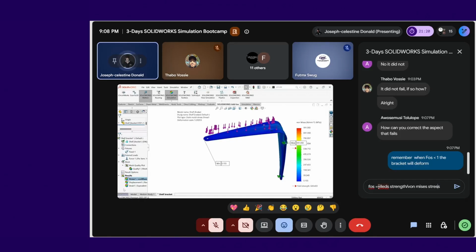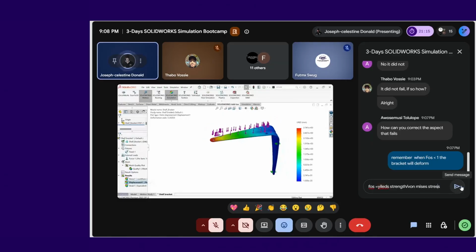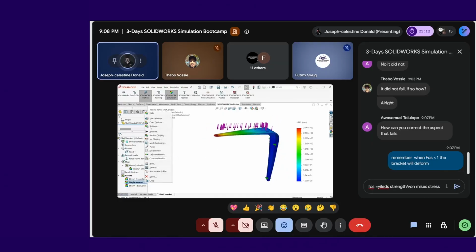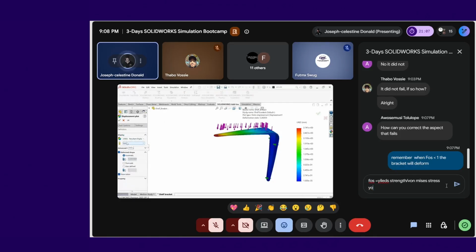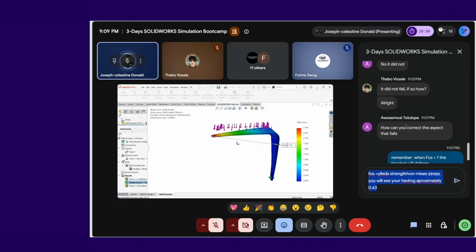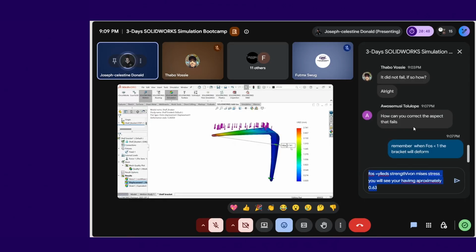Okay, now displacement. Double click and you get displacement. You do the same thing: right click, edit definition, so you get a proper value. It's in millimeters, so you select where your maximum displacement occurs, and then in the chart option you use floating so you get a proper value. So you can see that it has a maximum displacement of 2.74 millimeters.